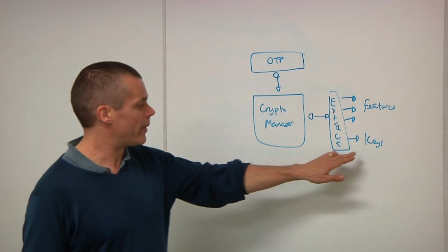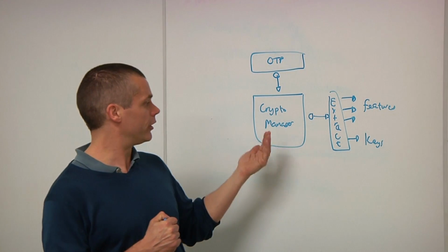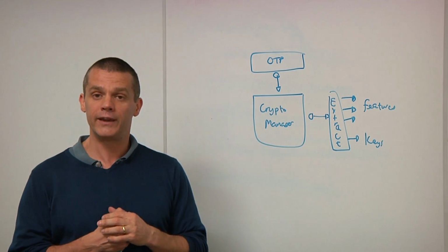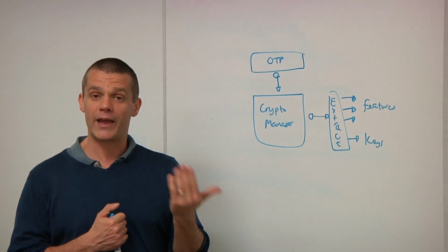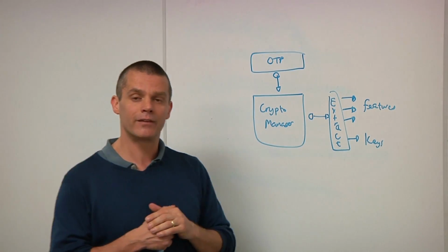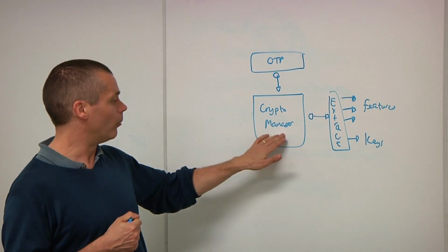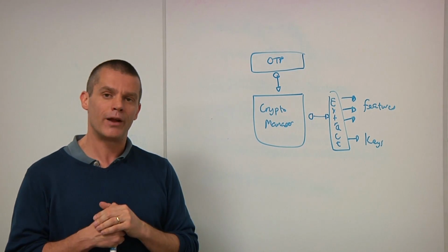And then the bank's application can identify itself to the root of trust and provide the command with the encrypted key in, and provided the crypto manager state machine confirms it's the application that owns the key, it can either provide the key back to the application, or on behalf of the application, it can actually keep the key but use it to process transactions.